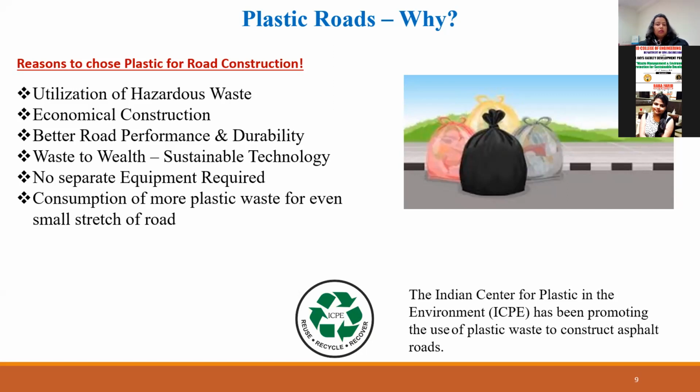The road parameters which express the performance later on in the O&M stage, and also the durability, the wear and tear, the fatigue, the strength, the Marshall strength properties, the flow properties, the occurrence of stripping in bitumen and aggregates, the occurrence of potholes. All these have been witnessing a great improvement over and above the conventional mixes.